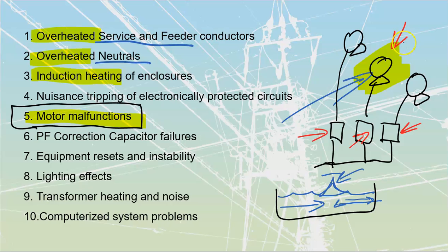But super hot motors that whine a lot, those are going to be, once again, usually magnetic issues. You should be familiar with what a magnetic whine sounds like at this point. When you start up a VFD-driven motor, it will always have a certain amount of shrill, high-pitched frequency to it. But there's also a lot more rattly noise that's usually a bad sign. Anyways, lots of motor malfunctions that we're going to get off of these ones.